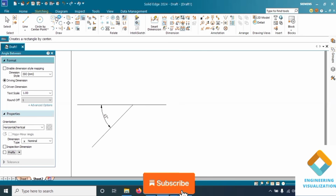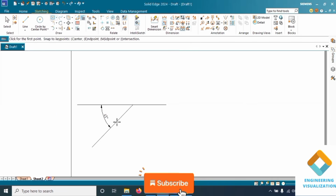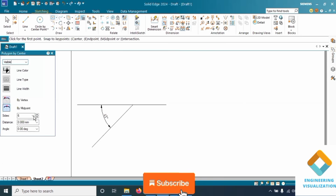Now we have to go to the polygon base center command. So construct the pentagon with the edge. So here number of sides we need to take 5. Place it with the edge.